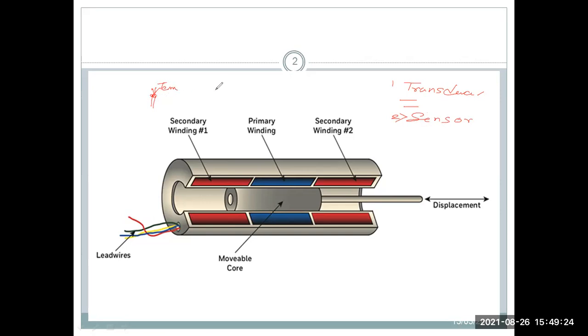But for our controlling purpose, measurement instrument, we need to make it a signal. So the first sensor is, say, RTD. You will read this word RTD. TC means thermocouple, and RTD is resistance temperature detector. It will sense the temperature, meaning it will produce some electrical signal.